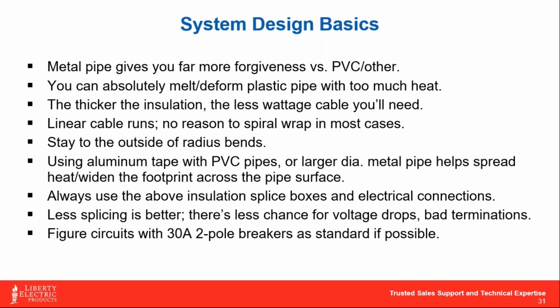If I'm using an 8 watt a foot cable for a 5.5 watt a foot application, I've got no problem there, because the metal will take it. In PVC, you've got to watch how much heat you're putting on it. The thicker the insulation, the less wattage cable you'll need.